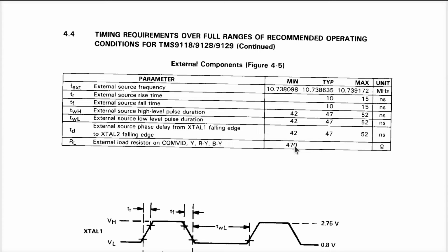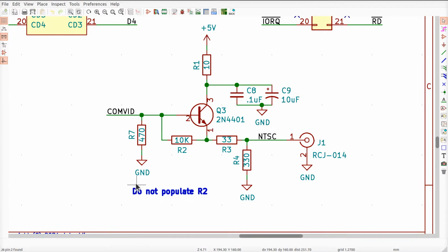So what to do? Well, I decided to do this. These are like 4 different designs, the union of 4 different designs, all in one laid out thing. And we can either populate or not populate various parts or short them out and stuff like that, and play around with some games here. I did some of this with my breadboard, and I could see various differences, but the noise was enormous, and breadboards are noisy, and I'm like, let's just make a board and see what happens, all right? So I just threw everything on here. Here's what we're going to do.